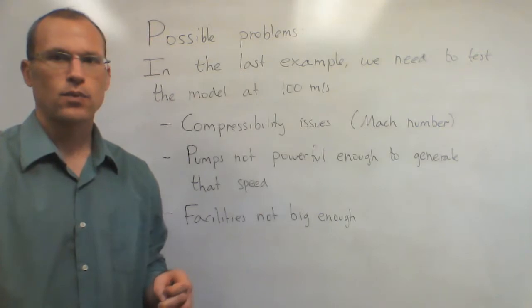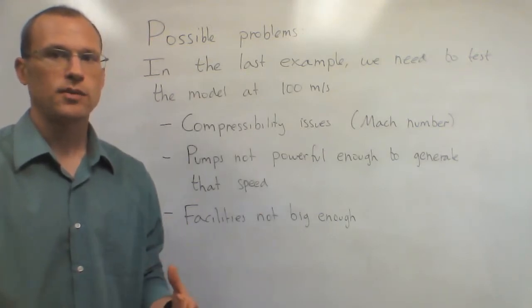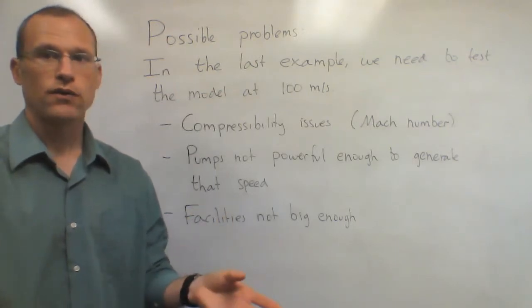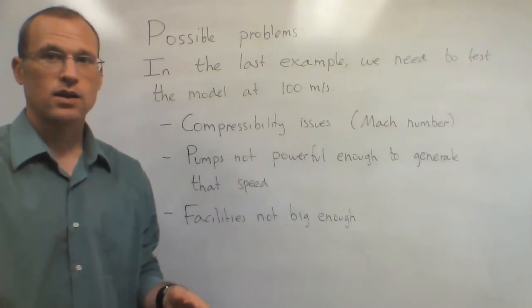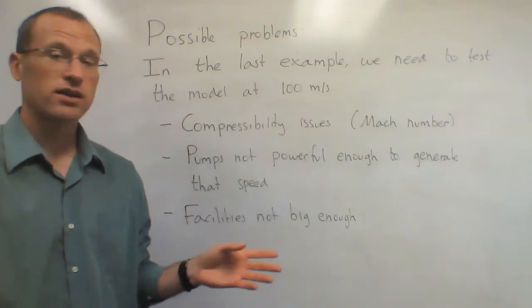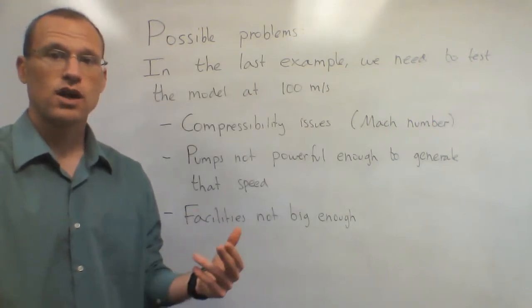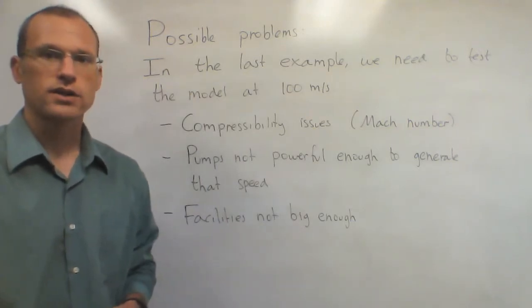So remember, we have to take into account all of the important parameters for our problem. We only took into account Reynolds number and coefficient of force or pressure. When we get up to higher speeds, compressibility becomes an issue, and so you should actually have the Mach number in there as well. And so we should not only have the same Reynolds number, but also have the same Mach number, and that's not going to be the case if I have different velocities.